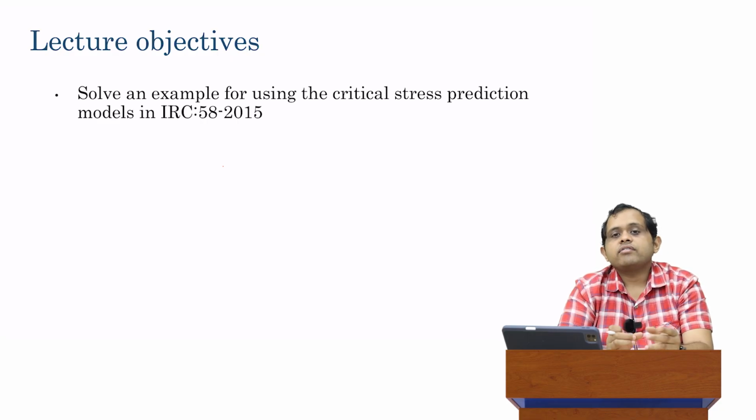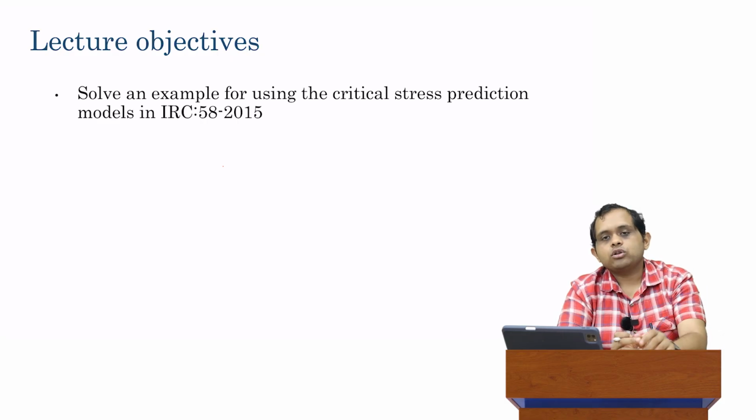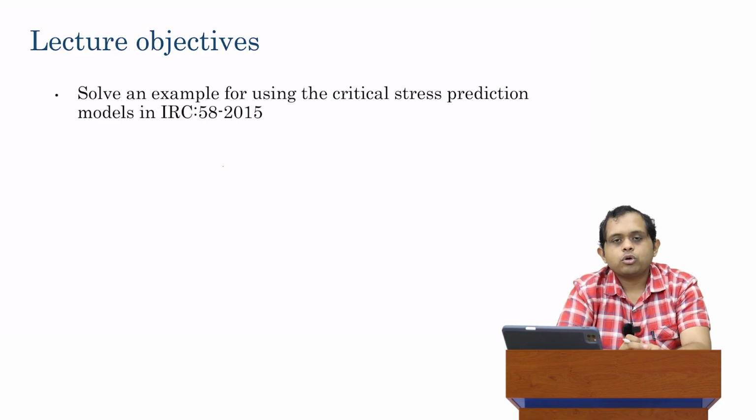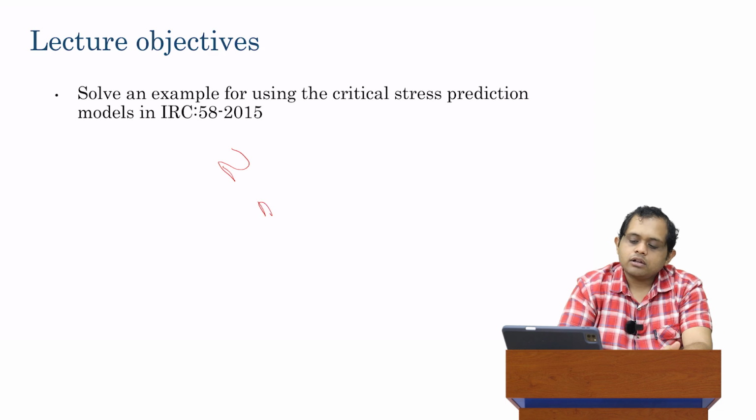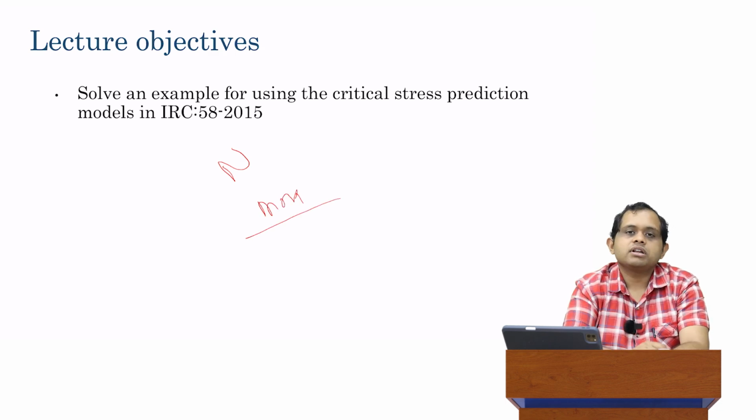Previously, when we looked at Westergaard's theory, for example, it was ensured that all the results were independent of the units, except for one value, which was generally the load. You just had to make sure that you were unit consistent. And generally there I had told you that you should use loads in newtons and lengths in millimeters. If you do this, for Westergaard's theory, you would be fine in using the equations.